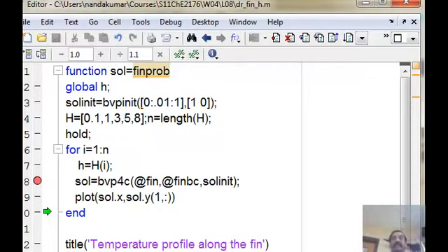So what does it mean when I say theta equals 0.8? Suppose I give you this problem. Theta is 0.8 and T0 is 200 and T infinity is 25. Find out the temperature. How would you answer that question? You have a solution. This is a graph which says when the heat transfer coefficient is 0.1, the dimensionless temperature is 0.85. Okay, from this graph you get that. And then I ask you to calculate the dimensional temperature. What is the real temperature in the fin? How would you do that?